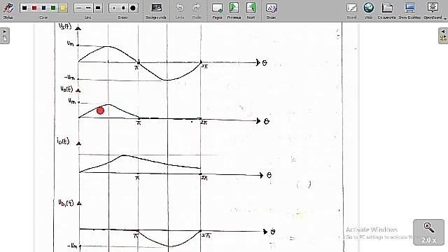In the previous case, from 0 to beta the main diode was conducting, but now only from 0 to pi the diode D1 is going to conduct. When the diode D1 conducts, the source voltage is equal to the load voltage, so it is going to follow the source voltage. From 0 to pi the current is going to get charged in this case. And as the diode D1 was conducting, its voltage is equal to 0.